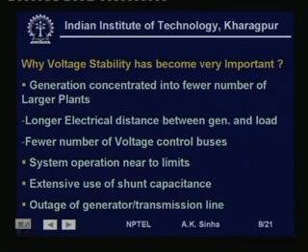One more reason that has been there is the use of shunt capacitors. We have been using shunt capacitors extensively in trying to maintain the voltage under normal operating condition, as well as to reduce the maximum power demand and improve the power factor of the load. So, most of the load points we have shunt capacitors available, but during heavy load conditions,